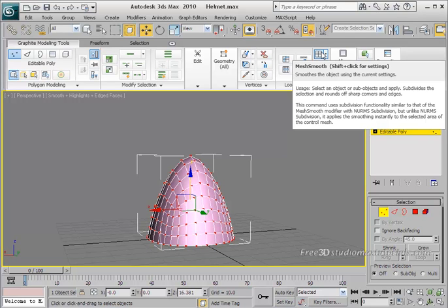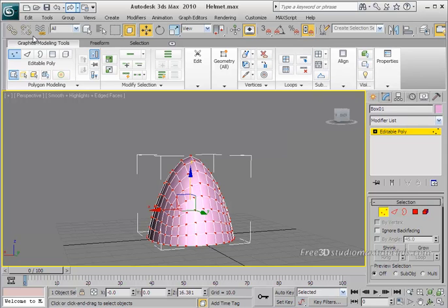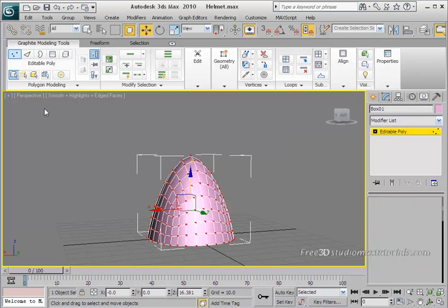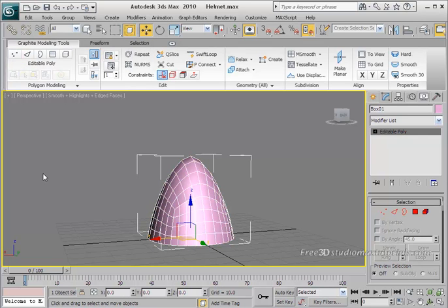On the ribbon, just go to the polygon modeling panel and then click on vertex to exit this selection mode. Now at that point, just save your scene with whatever name you want to give it. Okay, now you will work in symmetry mode on half the helmet. This way, any change you make will be perfectly mirrored for the other half.